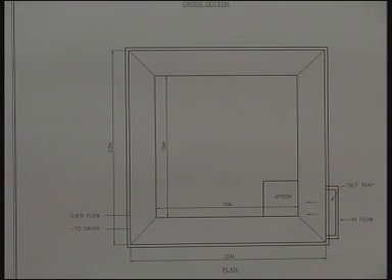The capital cost of works also would get reduced, because in any given situation in an urban area we have nearly 600 to 800 mm of rainfall per year, and considering that even about 1/3 of it goes for recharge to groundwater in the urban area, there is no need to get water from anywhere else, from any stream nearby or any faraway place, because the groundwater itself will be able to supply the drinking water requirements.